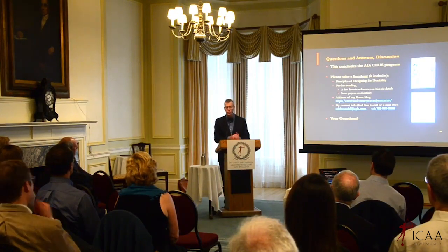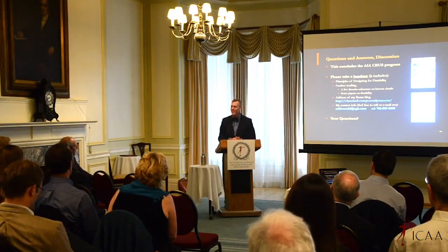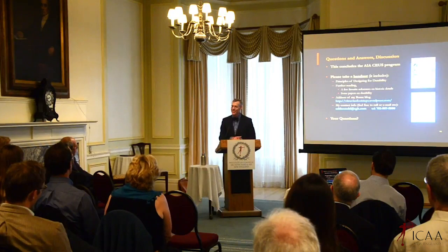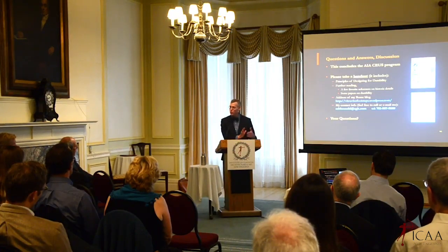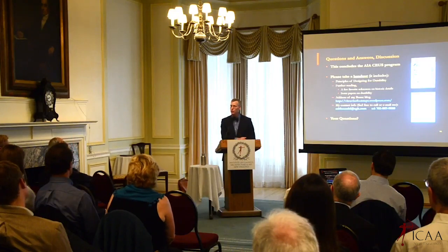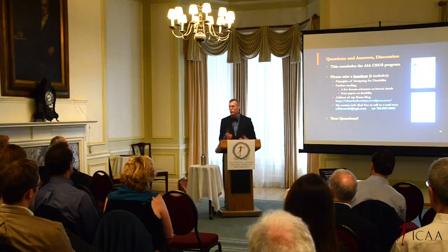So, I think another good lesson for durability that a lot of the brutalist concrete architects could have learned is that concrete's most durable if you don't expose it to the weather. I think they were really being honest about the structure, but the Roman structures typically had that sacrificial parge coat of stucco, or sometimes brick facing, as the outermost cladding, just because of the greater durability of, say, brick or stone, or the sacrificial nature of the stucco, which would be easy to fix without getting into structural damage to the bearing part of the wall.